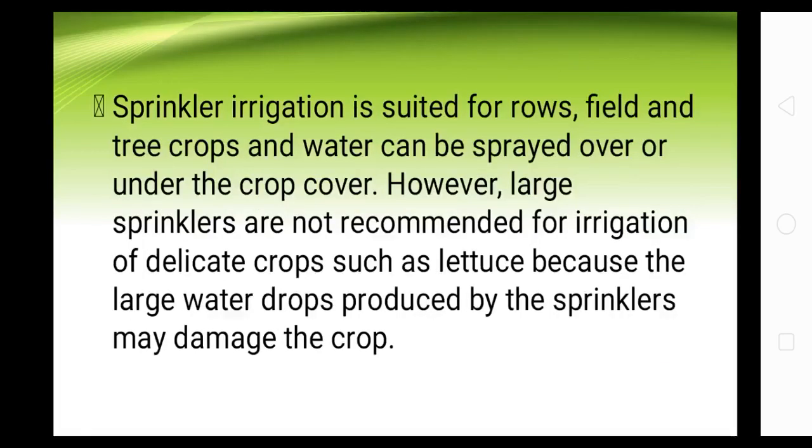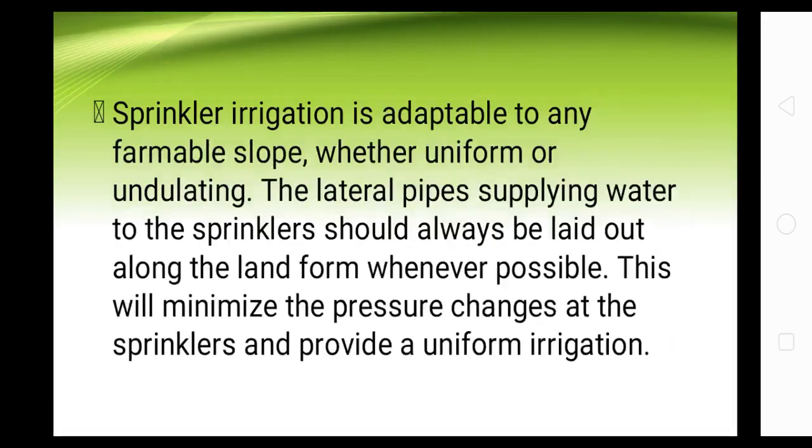Sprinkler irrigation is suited for rows, fields, and tree crops, and water can be sprayed over or under the crop cover. However, large sprinklers are not recommended for irrigation of delicate crops such as lettuce because the large water drops produced by the sprinklers may damage the crop.